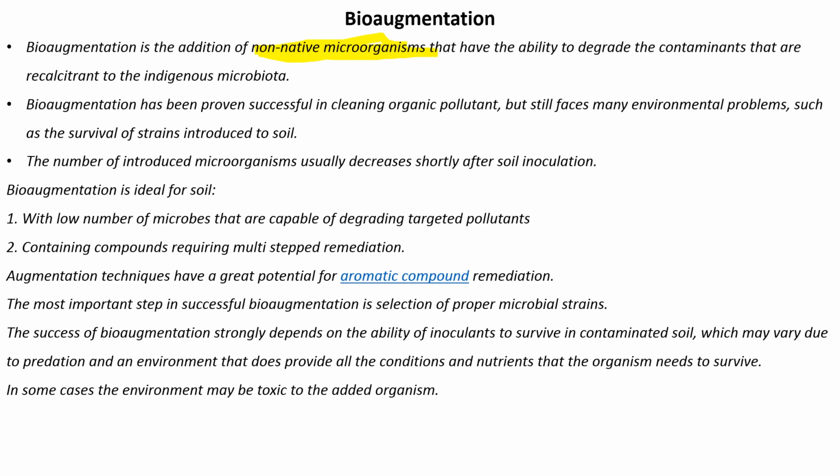And we take this lab generated microorganism to the particular site of pollutant, or we take it to the treatment plant, we add it as bioaugmented bacteria or fungi and make sure the pollutant is completely mineralized in a particular time interval. So in treatment plants, when we use bioaugmentation techniques, we make sure that we continuously monitor it so that the biodegradation is complete by a particular time interval, so that the process is working well and is very, very fast. That is very essential when you are going to add a bioaugmented bacteria.